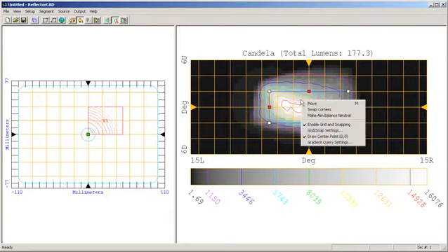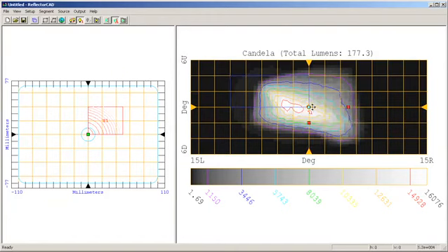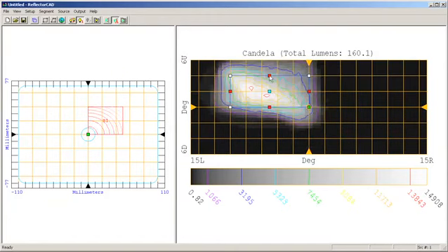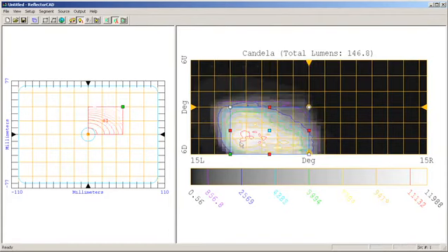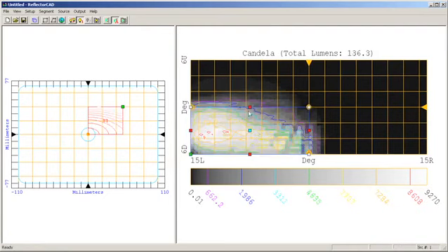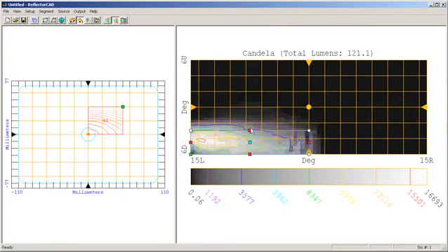In fact, I will actually operate on the luminous intensity pattern, changing that pattern to the desired shape that I want from that particular segment by dropping and dragging the various areas around the luminous intensity pattern, and ReflectorCAD will automatically update the shape of the segment in order to produce that particular luminous intensity pattern.